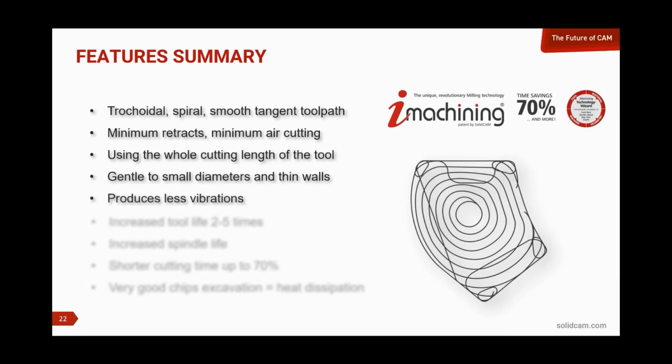This produces a lot less vibration because the tool and the material are never seeing what we call a linear force vector. They're only seeing rotary torsional force vectors. And so the vibration is significantly reduced automatically. This increases our tool life, and we'll show some other things about this that really are very important.